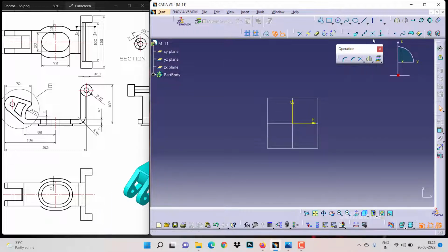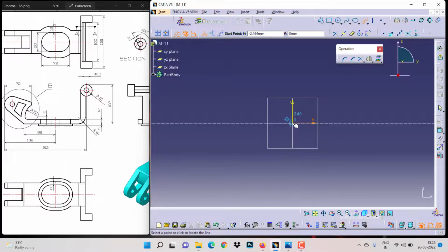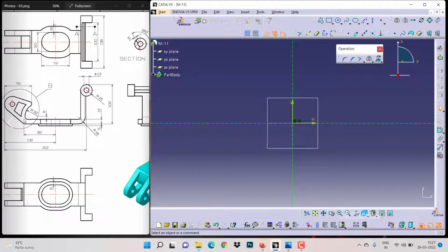So click on construction line, infinite length. So click on standard element as well. So place it on the origin. So once this is defined, consider this edge what we are having. So we are going to create the shape. So go to profile option. So before that, turn off your construction or standard element. So go to profile tool and create your shape.